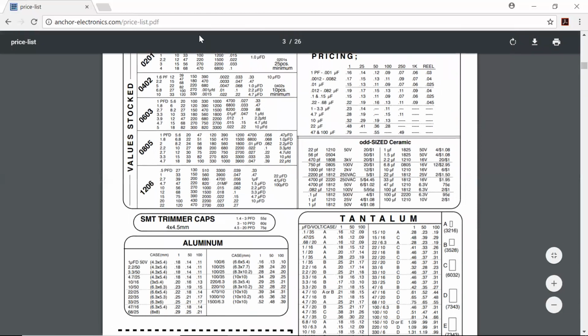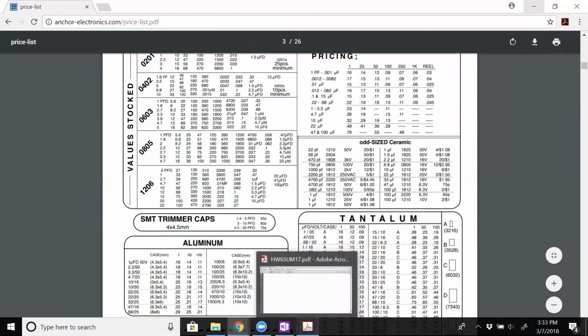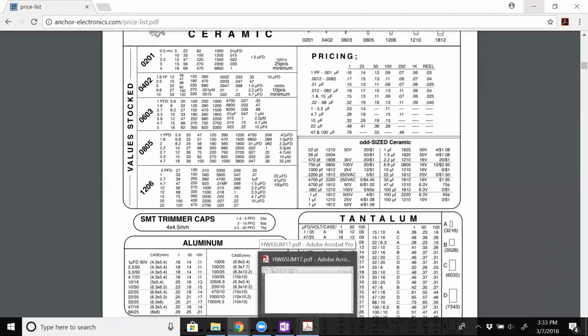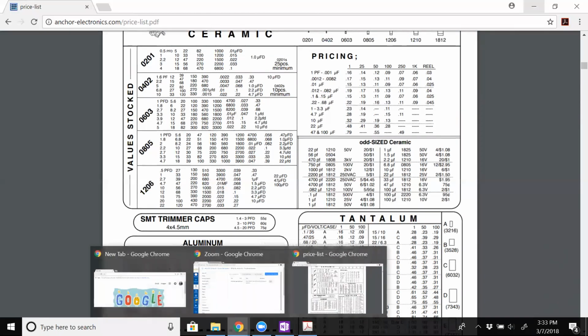I always like to use 1 microfarad. That's just me. When I don't have another condition on it, I tend to use the one that I always use, so I have them in my part bin already.